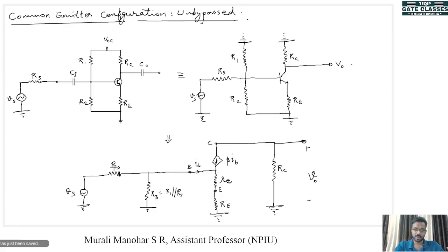Okay, now let's start solving for the important parameters that we know, that is input impedance, output impedance, voltage gain and current gain. So when you look from here, we have Rin. When you look from here, we have Rin dash. When you look from here, we have Zout or Rout, because I have already told you that these transistors will have resistances at the input, because all the capacitances are removed in the small signal low frequency analysis. So all these impedances are now just resistance, and that's it. So this is our equivalent circuit. I am redrawing it again for better understanding.